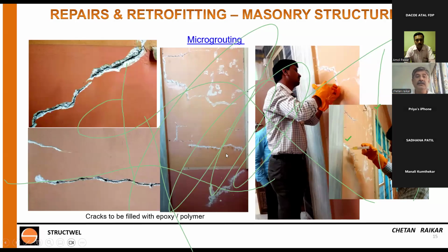If you see here, you can see so many syringes every 3 inches. We have just first put the needles. Here also you can see it. In this photograph also you can see every 2 to 3 inches. And through every needle, we inject the epoxy. It goes inside, it gets absorbed in the material, and the crack gets filled up properly. Any structure, any wall that has got cracking on both sides, symmetrical cracking on both sides, you can safely presume that these cracks are through cracks.